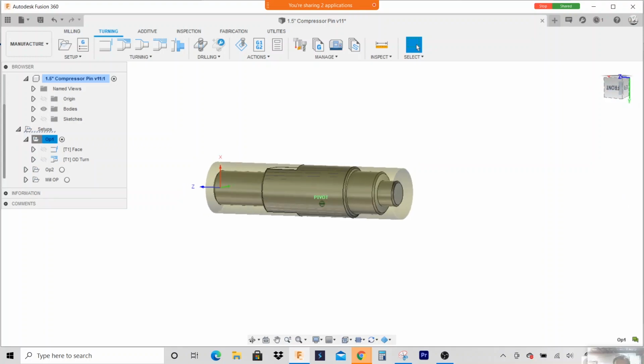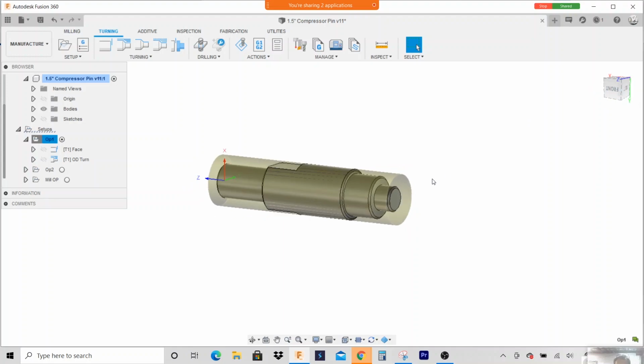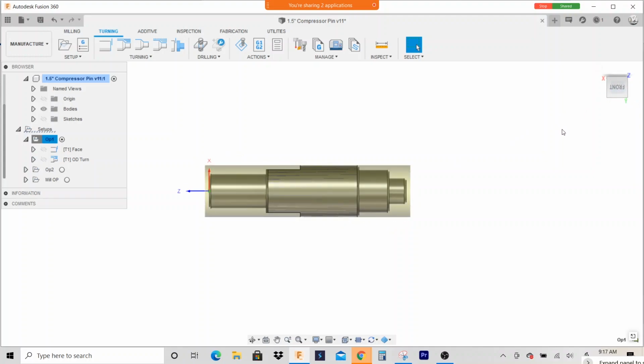Depending on the part process, sometimes you can speed things up. Sometimes it makes sense to do things a little bit differently if you're running 1,000 parts versus one. Like when I'm running one part, sometimes if it's just a part like this and I just have to make one, I won't even write a program for it. I'll just hand type some G code.